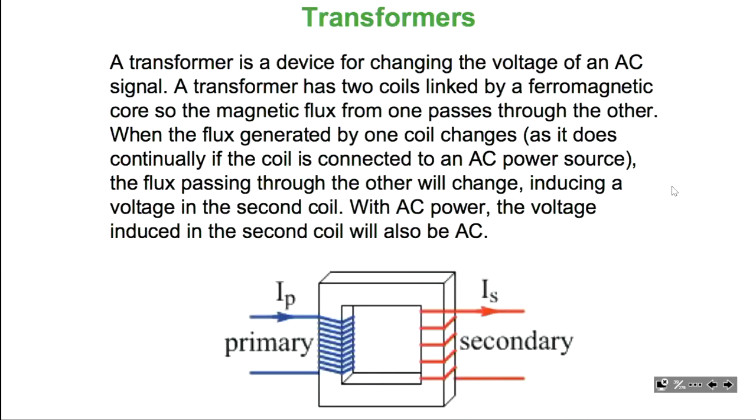Here, I have a function generator. I don't want to use the power outlet for alternating voltage. Is it on? No, it's not on. And this device will measure voltage, but it has to measure alternating. Okay, and same with this one. So I have to switch from DC to AC. Now, of course, nothing is happening. Nothing is connected to anything. First, I have to connect this generator to a transformer.